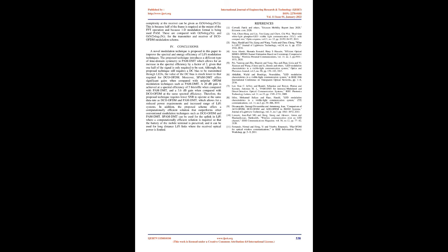This is because half of the frame is required at the output of the FFT operation and because a 1D modulation format is being used. These are compared with O(N log2 N) and O(N/2 log2 N) for the transmitter and receiver of the DCO-OFDM modulation scheme.